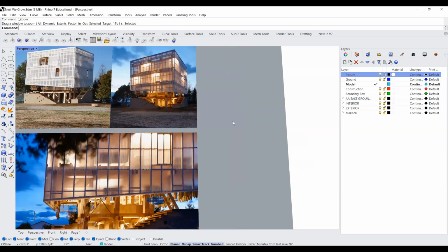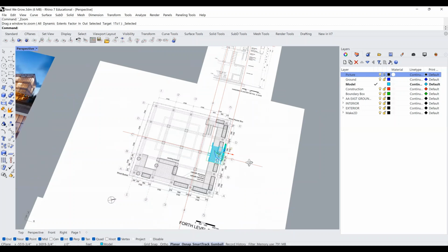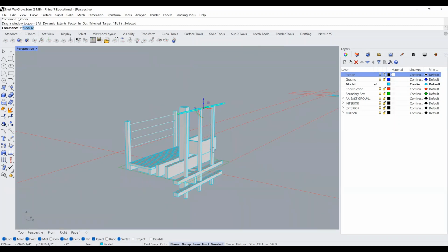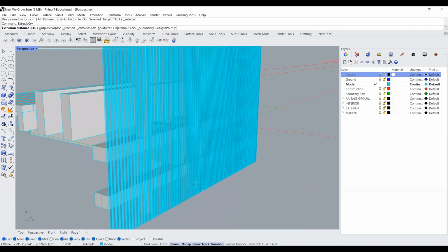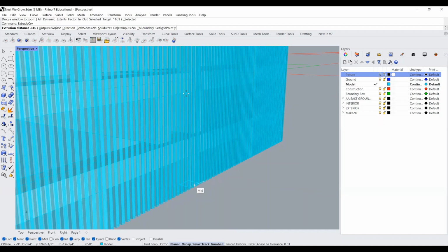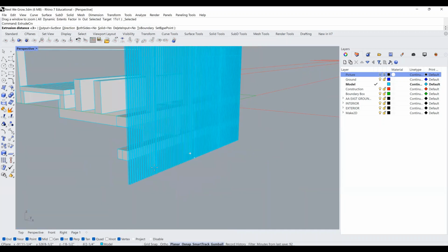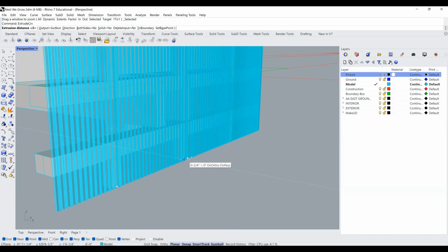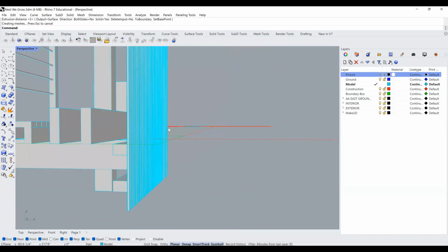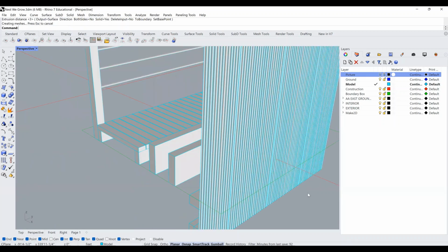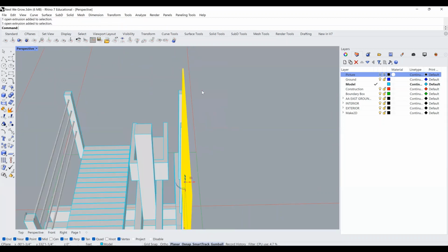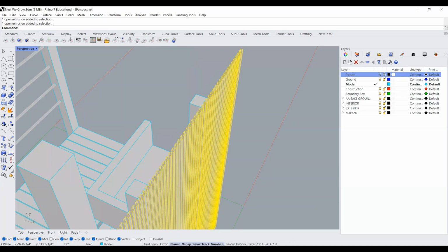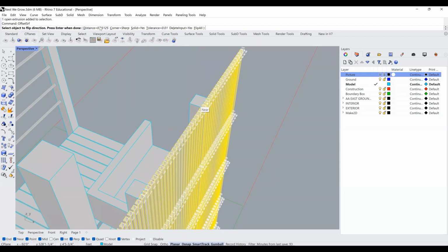And so the way that I'm gonna do this is, for now, I'm just gonna turn this off. And then I'm gonna extrude this all the way to the bottom part of my boundary that I set. Again, it's a 2-foot drop downwards and a 4-foot drop upwards, right? So it's a 6 by 6 by 6 cube that I'm modeling. And so I'm just gonna go all the way down to the extent of that framing element right there. And then to include thickness, because currently this doesn't have thickness, I'm going to type in offset SRF. And then I'm gonna choose a 32nd of an inch thickness.